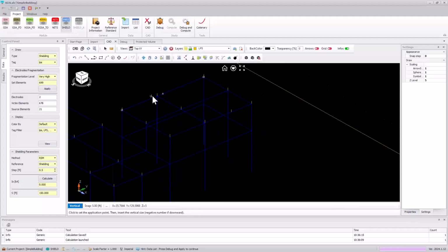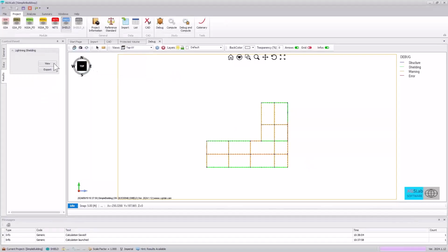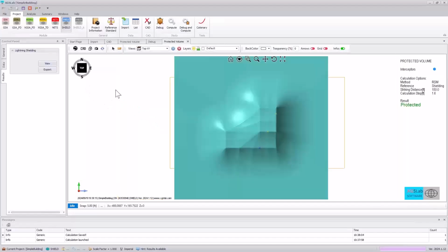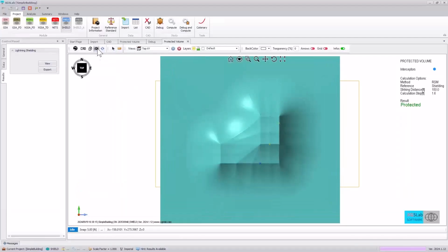So now we have more air terminals that we've added based off of our calculations, and we'll just rerun that analysis so that we can get to a point where we're saying this site is proven to have a protected zone so that any direct strokes will not directly hit our structure. And what we'll do is provide a view of this. So now we can see this is the protected zone. We can do kind of a top-down view of this system. Take a snap of that.